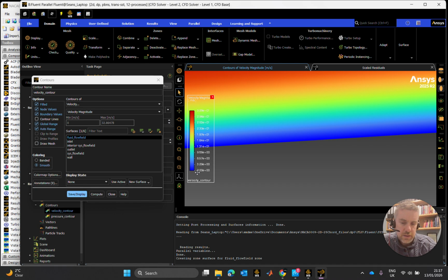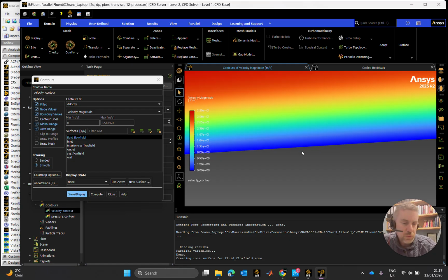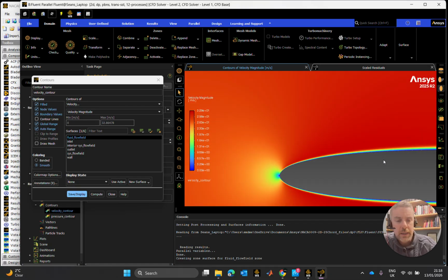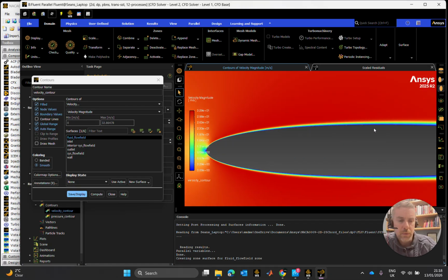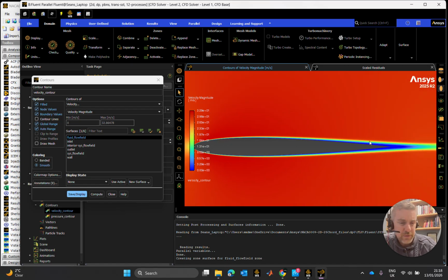And what we can see pinned up to the surface here is this blue region which abuts the surface, and that translates back into 0 meters per second, which gives evidence of a no slip condition, that at the surface that laminate of air effectively is stuck to the surface and it's gripping it. It doesn't want to let it go. That's drag. So that's friction drag, and that's one component that's going to slow us up. And for that reason, the longer the top surface is, the longer the bottom surface is, the more drag you're going to get.